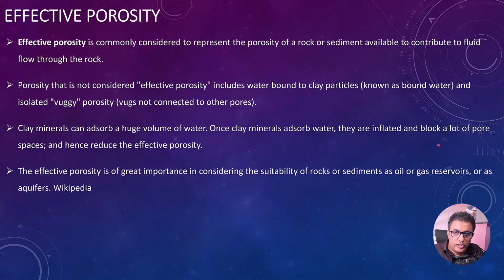There is a strong attraction between the water molecules and clay particles, and because of that, if the water molecules are bound to clay, they cannot move. So it is another example of porosity that is not considered effective porosity.